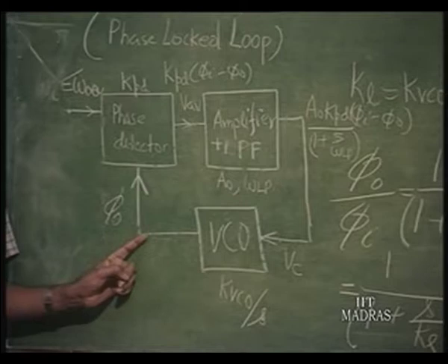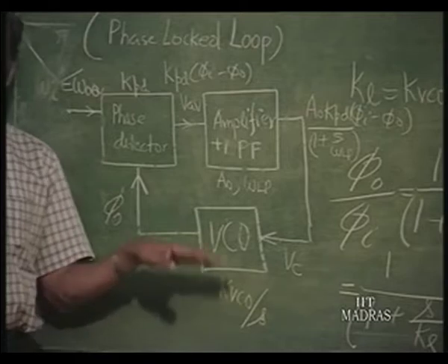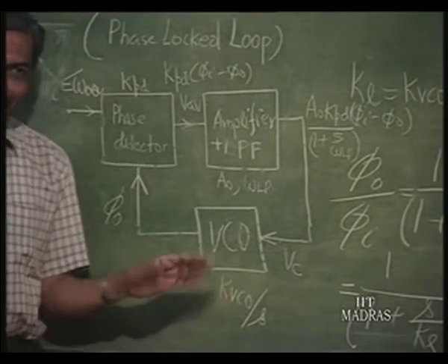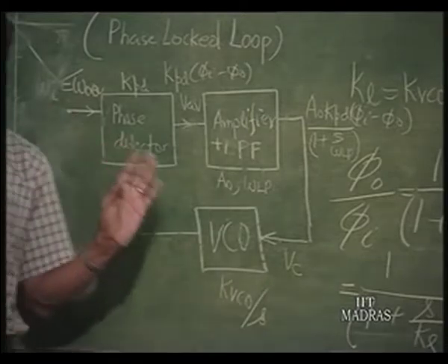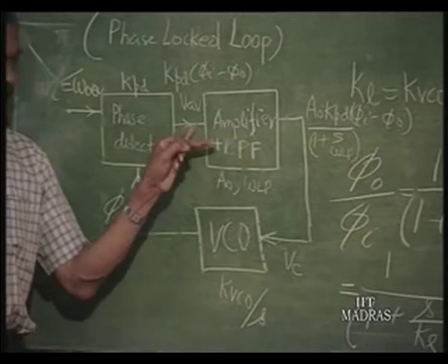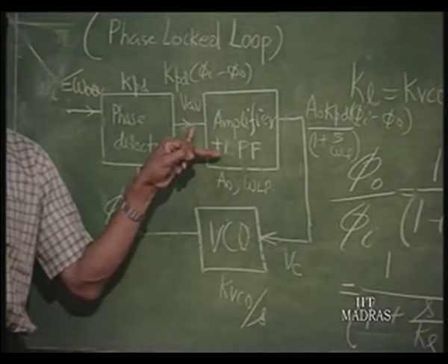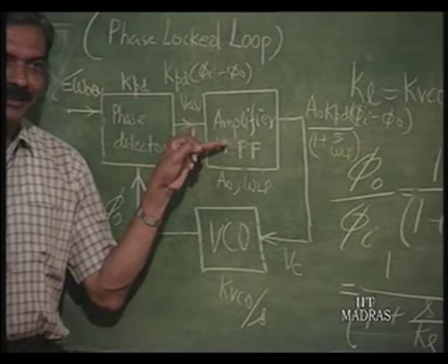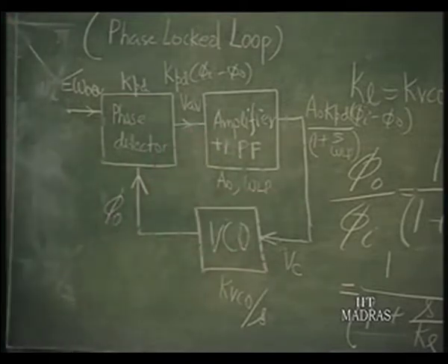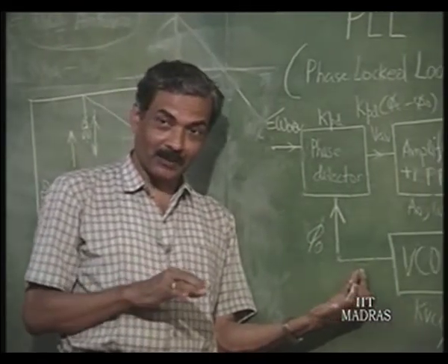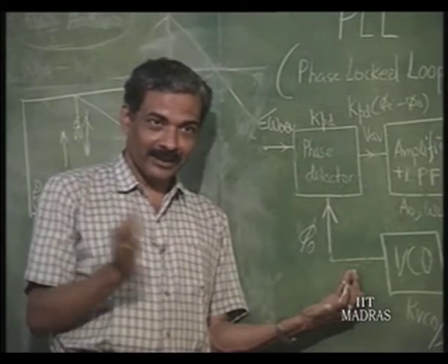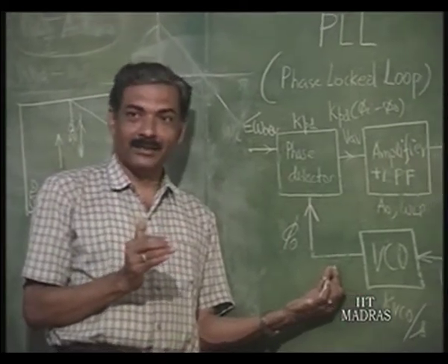The whole phenomenon of capture is again nonlinear, because please understand, the moment this particular frequency changes, I cannot consider this any longer that it is changing around omega naught q. At every instant of time this will be changing, coming closer to omega I and going away from omega I also. And correspondingly this frequency is not a single frequency, it is also a change in frequency. So, it is not possible to explain this until you accept the fact that this omega naught q is the quiescent frequency, and around this point it is going to change on either side equally.